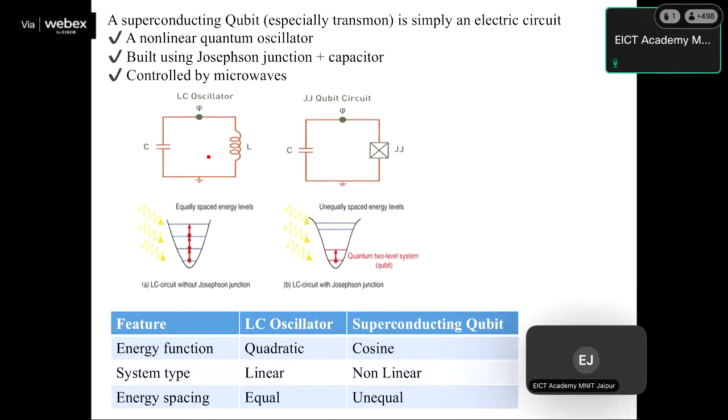The basic LC circuit consists of L and C, and the energy oscillates between L and C. The capacitor charges through the inductor, which stores energy in the magnetic field, and then the magnetic field circulates the energy back to the capacitor and charges it again.